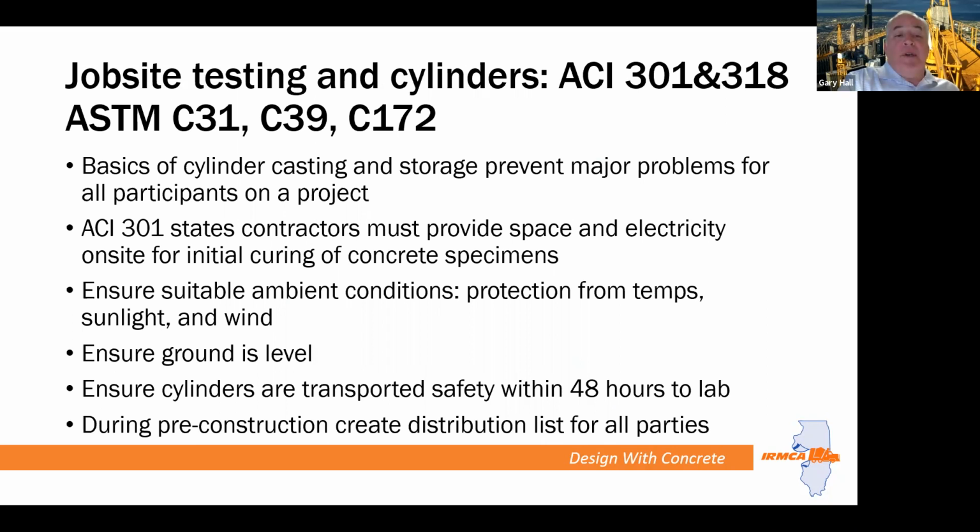So as far as the job site, we do have specs and codes that cover the casting and protection of concrete cylinders, because as we know on the job, concrete strength is the major mode of acceptance for the quality of the concrete. So we want to take extra care to make sure that the casting and protection of the cylinders is done according to the codes and specs. And cylinders seem to be a common problem in terms of low breaks that could be easily resolved.